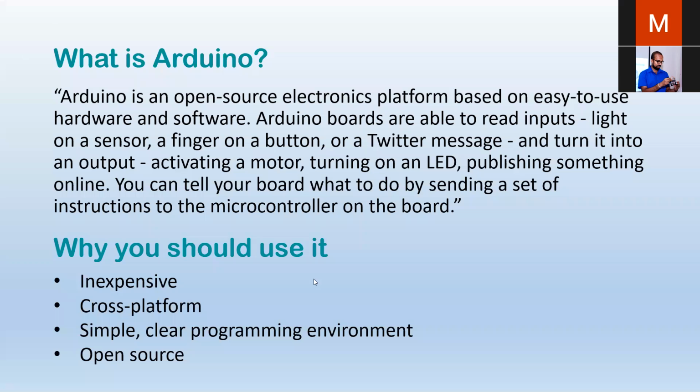A basic example I can tell you, which is more familiar to you, is that you might have heard about the circuit called the multivibrator. That is a circuit which has two LEDs, right? These LEDs toggle between one another. So when this is on, this is off. When this is on, this is off. It happens repeatedly. This circuit is constructed using two transistors, four resistors, and two capacitors, right? The on and off time of this are determined by the RC constant, which we call the time constant of a capacitor, tau, right? This is the time constant of a capacitor, and there are more equations to that, of course, but I'm just sharing the idea with you.